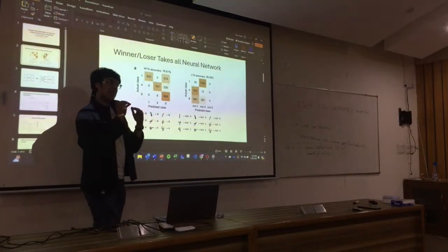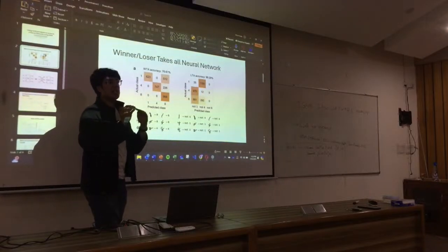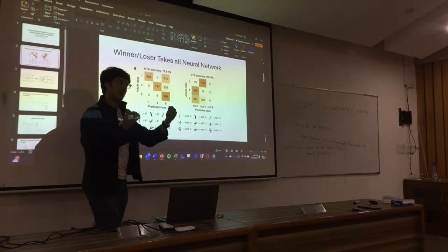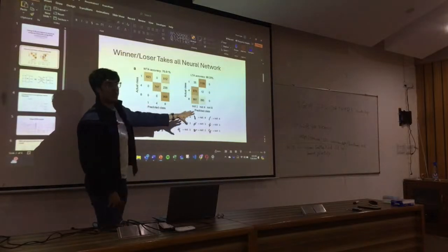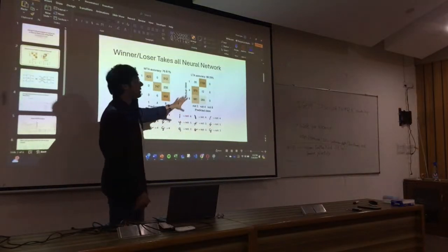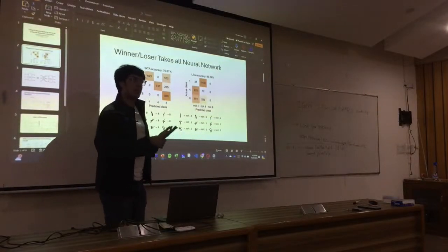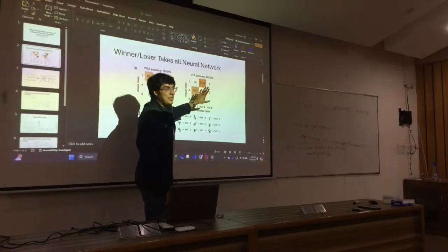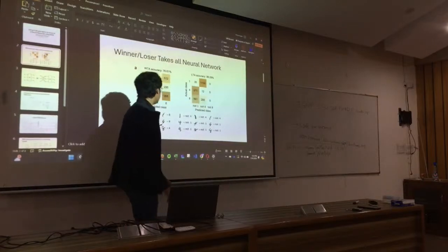Anything which exceeds the other values, the one for which recognition is more than competing values, takes all as the output, and the other values are ignored. Loser takes all does the opposite thing. The one for which there is lowest recognition is the one which fires the most. So essentially in this case, if 1 is output, it tells you the input is definitely not 4. That is what a loser takes all circuit does. Right.